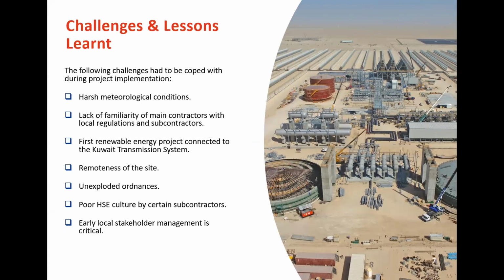On the solar part, of course, there was a loss of captured solar radiation, which impacted the project by requiring additional cleaning sometimes, or additional operation and maintenance costs that have been tested and verified during the operation and maintenance of the plant.